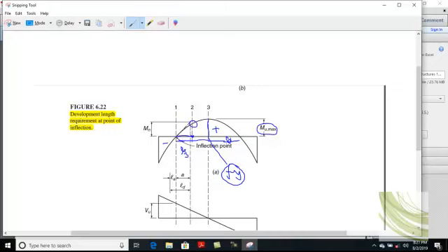So it says that you need to extend the bar both in this direction and in this direction, both right and left of this point, by a length equal to the embedment length to ensure against any kind of bond distress or bond failure. Clear?